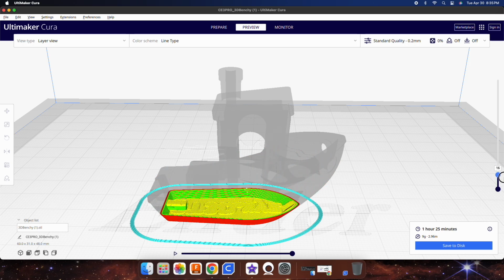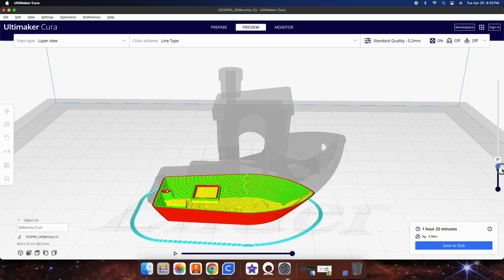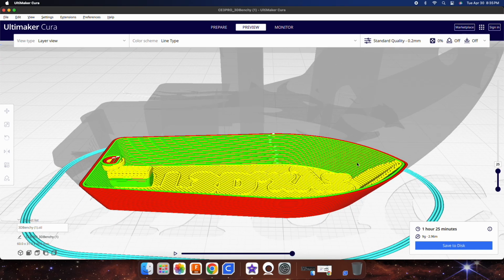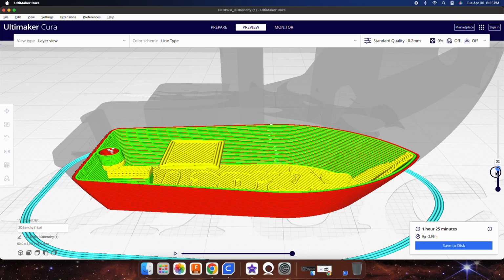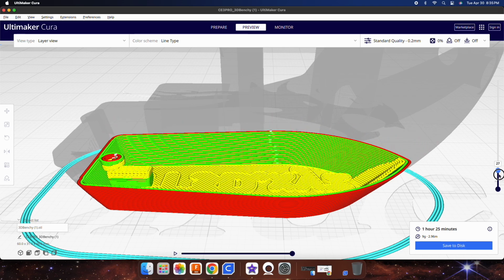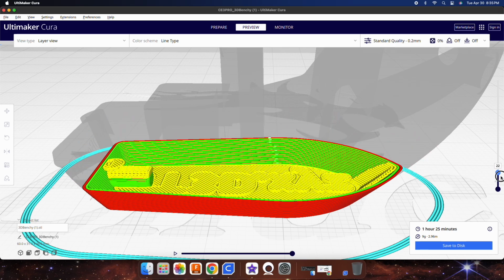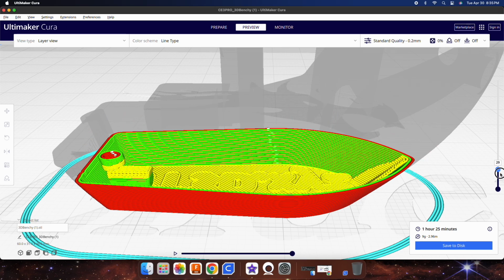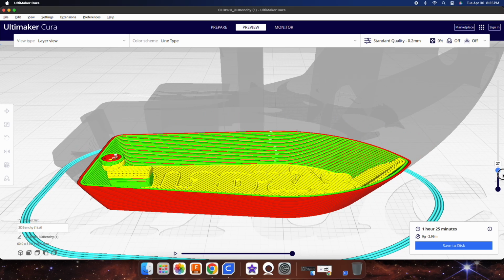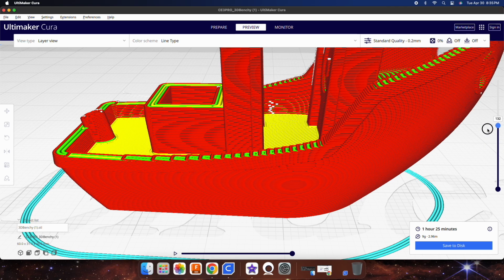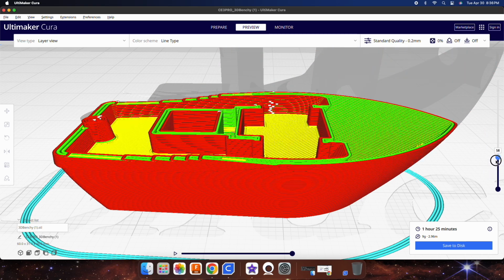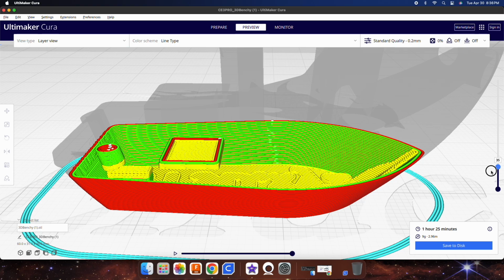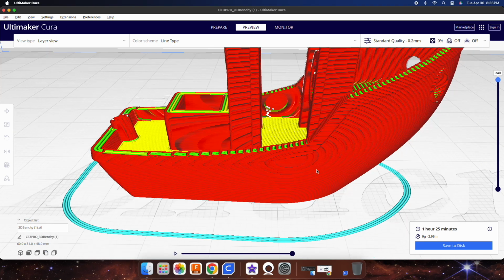And you can see because I picked 0% infill, it's just hollow, right? There's nothing in here. And that is not going to print very well because see right here, it just starts printing in the air. Even if it did somehow pull off printing all this, it would be really weak because it's just thin walls. There's nothing supporting it. So if we go back into prepare